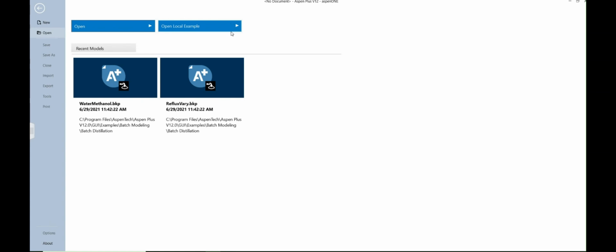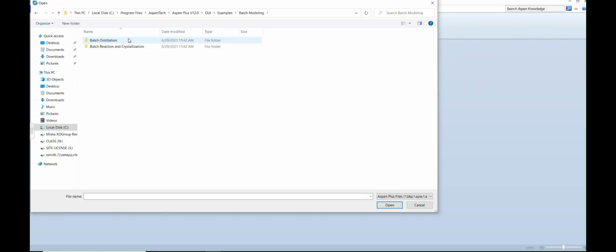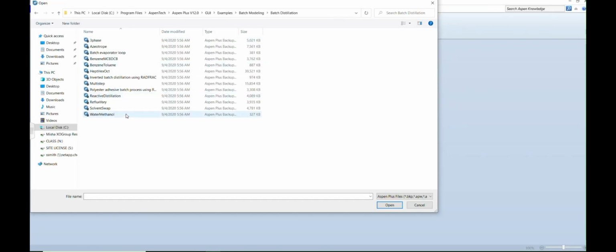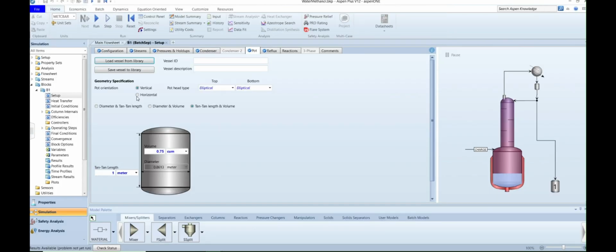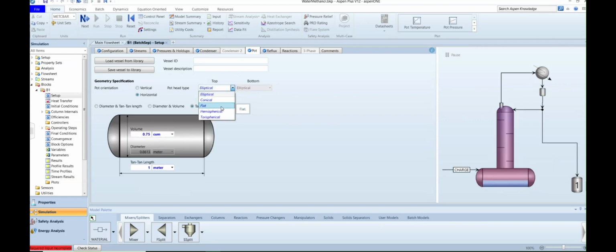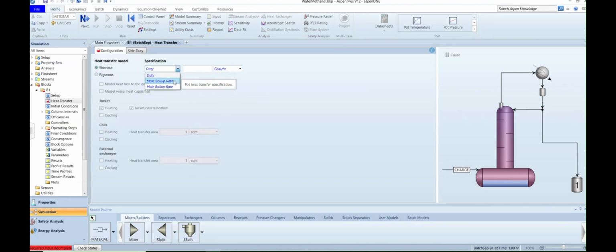To begin, we tried to model our process in Aspen Plus. We thought that this would be our best bet for our batch distillation process, as there was already a batch distillation model for the separation of methanol and water created within the software. We began using this and were even able to set the tank to the shape of the one we have in the senior lab. From there, we entered arbitrary values for the mass boil-up rate, as it was a required specification to run the software, but not a part of our project.